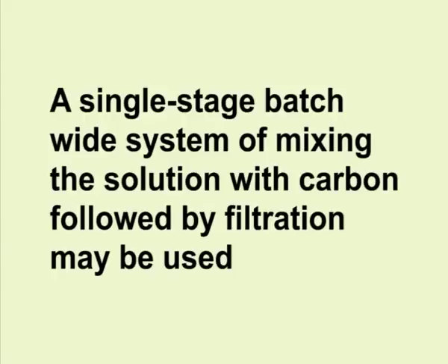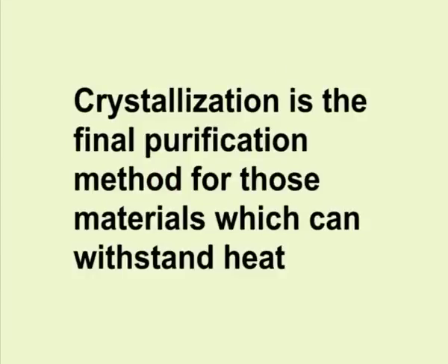A single stage batch system of mixing the solution with carbon followed by filtration may be used. Multi-stage countercurrent decolorization is far more efficient per unit of carbon than batch. Before using adsorbent, it is important to determine experimentally the most efficient depth of the adsorption zone which will thoroughly remove all color. Crystallization. Crystallization is the final purification method for those materials which can withstand heat.